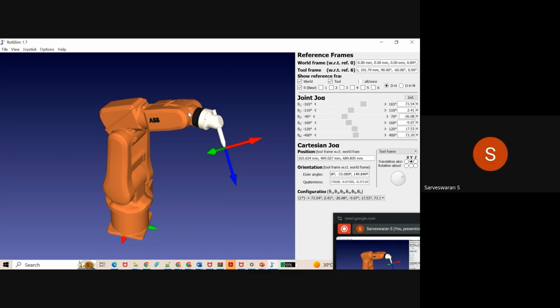For example, when you try to solve, you will find out here the torque required is 2 newton meter. So for this 2 newton meter, you have to select a suitable servo motor for overcoming this torque. So this is the opposing torque. You have to select your suitable servo motor. Suppose you buy a 2.5 newton meter torque motor for this joint 5.